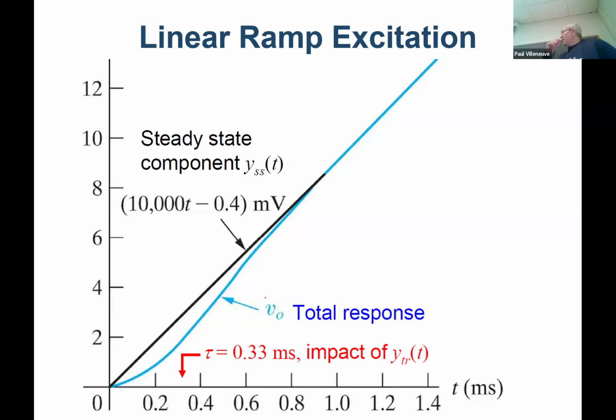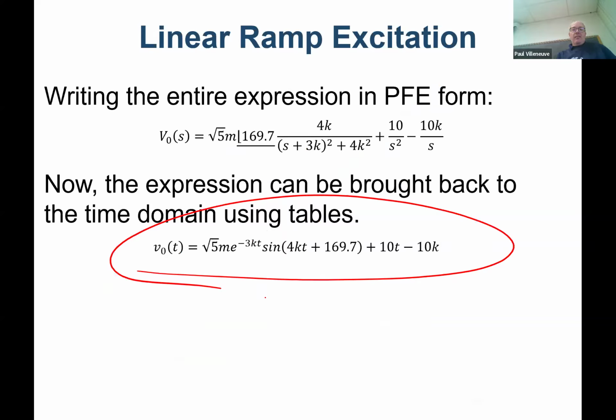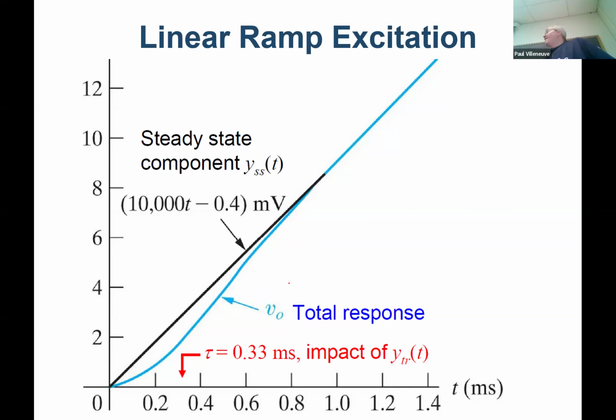And here's what that plot looks like. You can see you have a linear escalation, so that's the value of 50 times t. And then the blue line is the actual output. And so you can see there's a gap, right? Because you have this decaying exponential here that is making your life a little harder. So that's why you see the gap. And then eventually over time, they balance each other out. They would be at the same value. Okay?